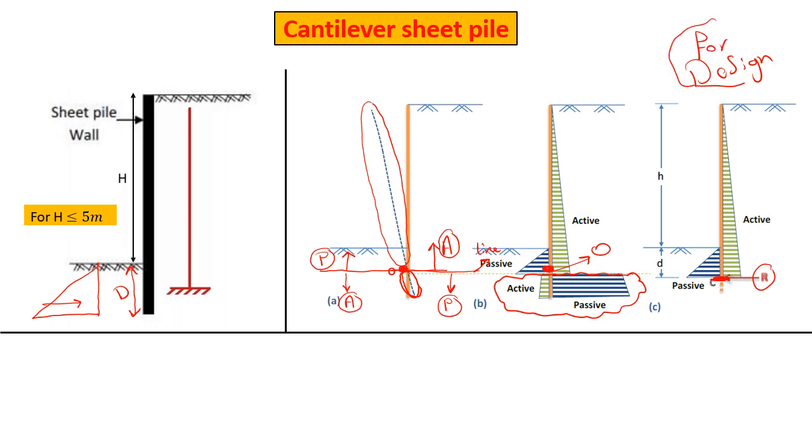We will assume that whatever lies below the point of rotation will be neglected, and that's by replacing all the stresses below the point of rotation by just one force, which is a resultant force passing through the bottom of your flexible retaining wall.